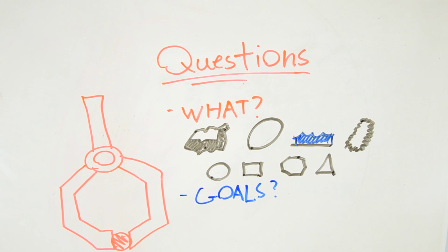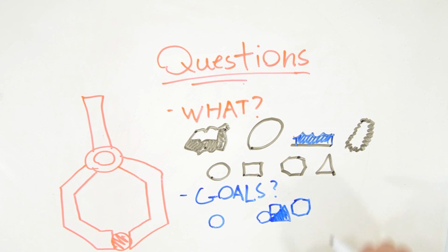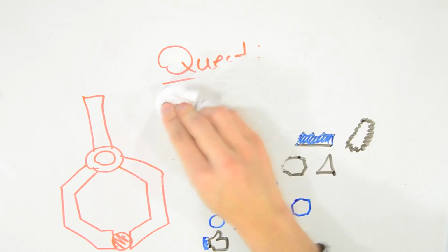So if your gripper needs to be able to grip ping pong balls, for instance, then it's way easier to design a gripper that specifically holds ping pong balls and nothing else. And it's much harder to design a gripper that can grip anything and everything. Both of these grippers will be able to grip your ping pong ball, but one is much easier to design. So when you can, make the task easier on yourself by designing for a specific case rather than a general one. So we should keep this general rule in mind when we try and establish the goals of the design.